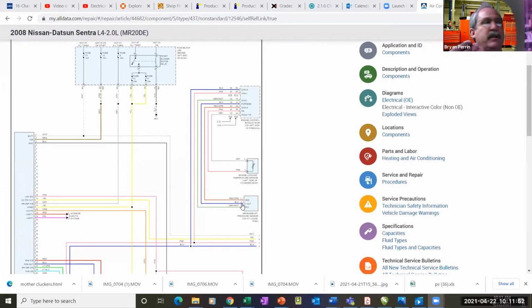If my engine cooling temperature says we're below 0, you're not getting AC. If I'm overheating, at 250 degrees, you're not getting AC, right? Because we're not going to turn the AC on a car that's running too hot." So I need to be in the normal range for my coolant temperature. And then you have pressure.